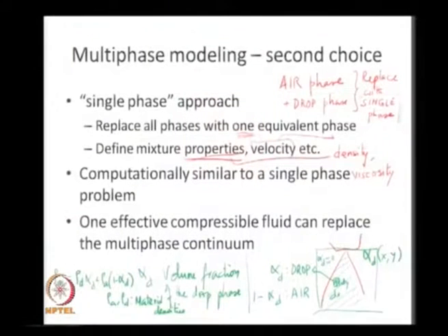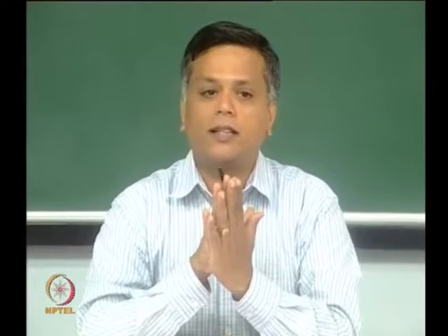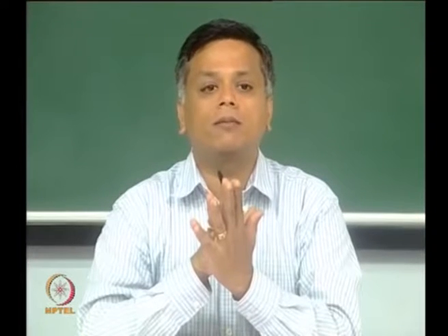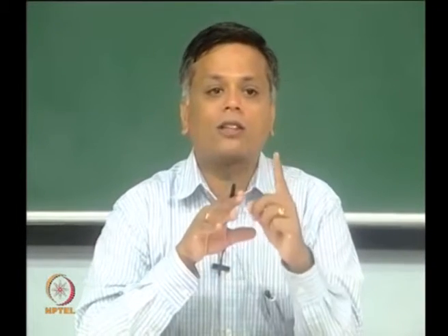Now, where I do this, this is not a huge assumption. Even the fact that I am replacing it with a third mixture fluid is not as limiting as the fact that we are only allowing one velocity field. So, essentially the moment I replace my two phases with a single phase and solve a single phase momentum and mass continuity equation, I am only going to arrive at one velocity field for this mixture fluid.